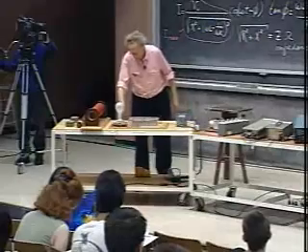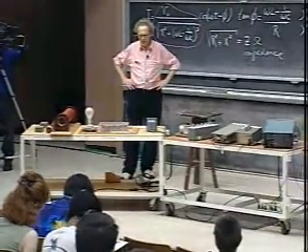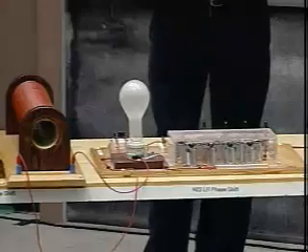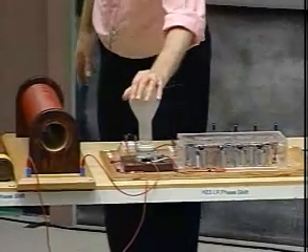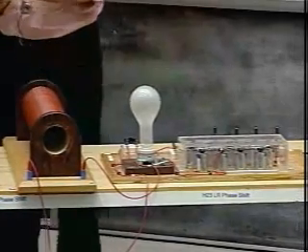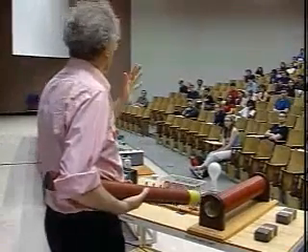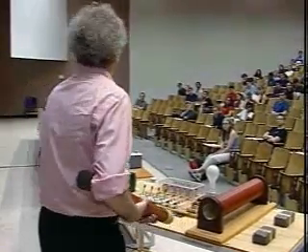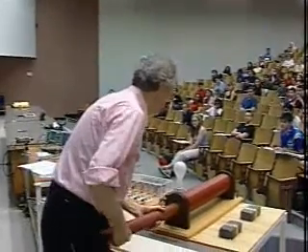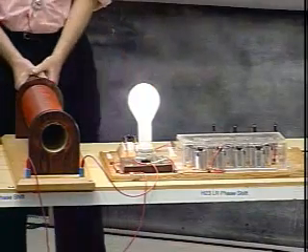All right, so here, the system is now, current is going. 60 hertz, 110 volts, root mean square, as we call that, and it's way off resonance, 7.5 watts. The light bulb doesn't even feel warm. And now I bring this enormous piece of iron in there, and when I shove it in, the self-inductance will slowly go up, the resonance frequency will shift, and the current through the system will increase. And there we go. There it is. I'm on resonance now. So the light bulb is quite happy.